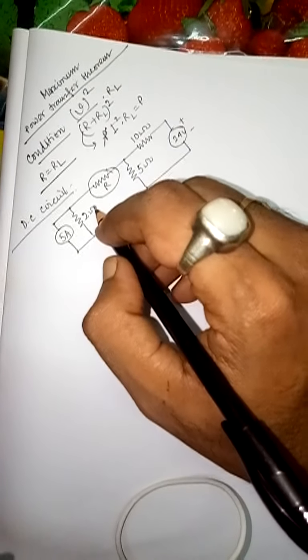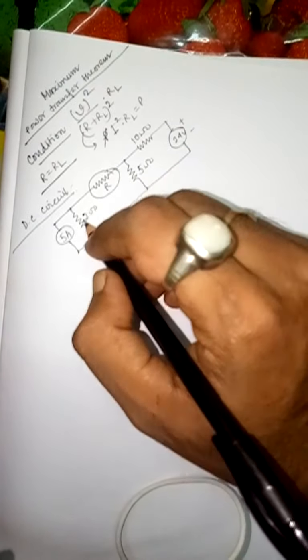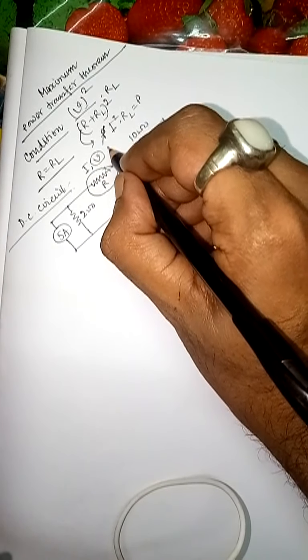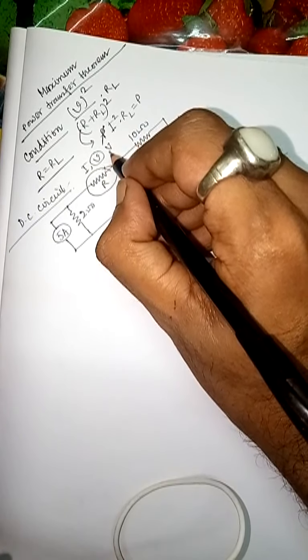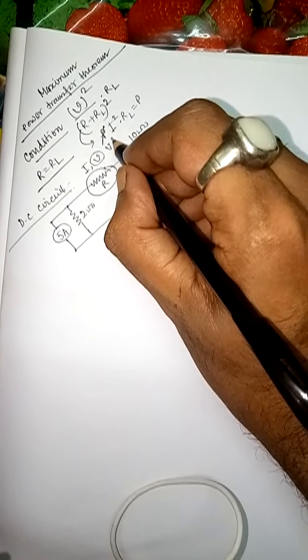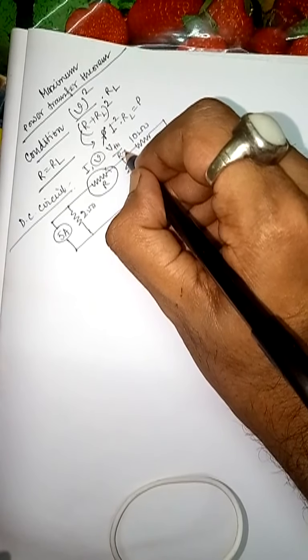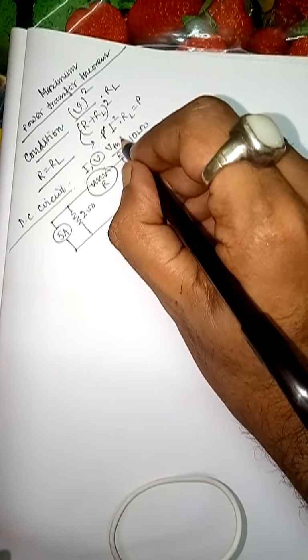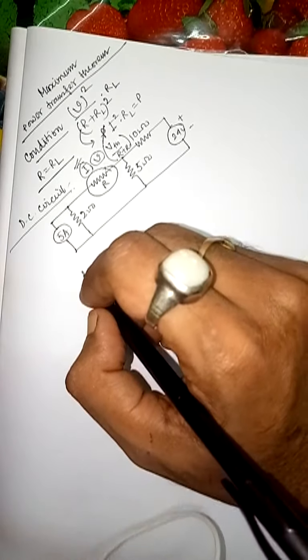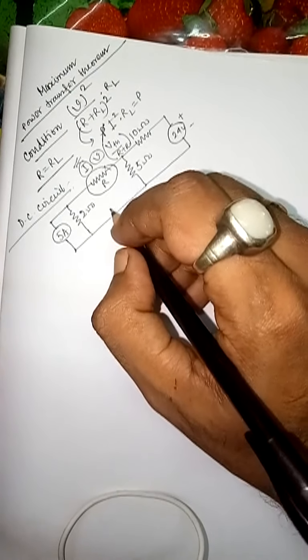Actually we have to use either Thevenin's or Norton's theorem to get the value of I or V. If you are getting V, V is the open circuit voltage, so you can write V Thevenin. So V square by R plus RL is the answer. That is a current, so obviously across R you can find it, or you can get that I using Norton's theorem. So let me apply Norton's theorem and let us discuss what drawbacks and problems people used to face with this.